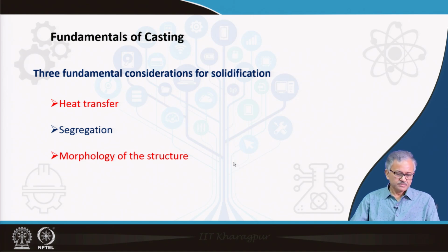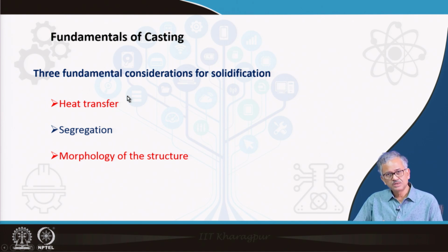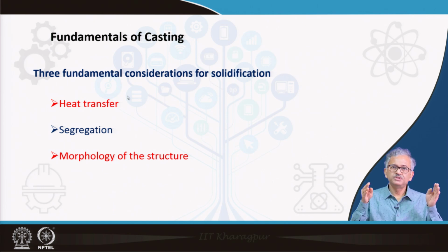So, fundamentals of casting: there are three fundamental considerations for solidification. One is heat transfer, because heat transfer basically gives you the rate of solidification, and the rate of evolution of the solidified shell with time.